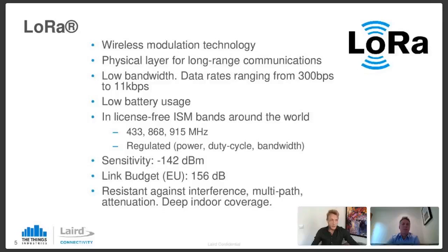We actually see a lot of use of LoRa, not necessarily because of the range, but really also because of the little use of power. So battery driven sensors that are installed somewhere in places that are hard to reach, or where it's expensive to replace batteries. I think in cold chain specifically, batteries can often be challenging in battery driven use cases. LoRa can be used for the range, for the low power, or a combination of the two.